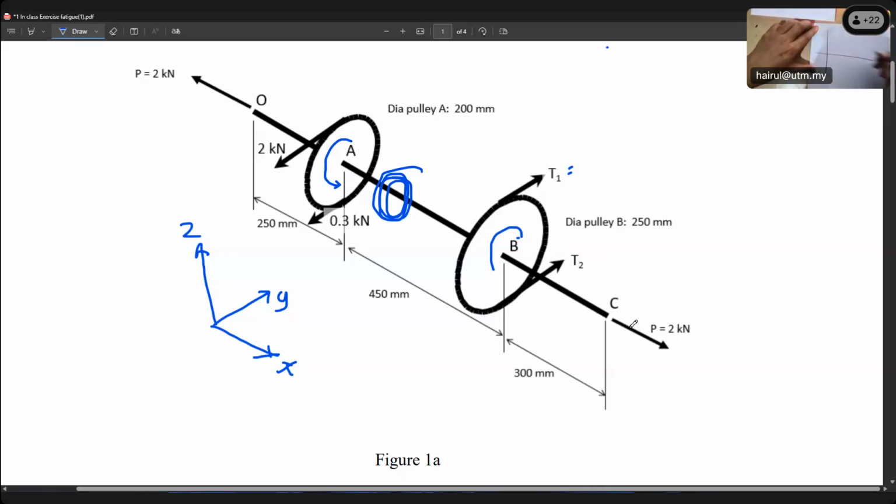Bending, why? Sigma bending. Remember as I told you, if you look here, because the shaft is rotating. This is your bigger shoulder. We are at the shoulder here. Can you see the bending? This is your smaller diameter D. This is the shoulder that you focus on, your element. Because the shaft is rotating,